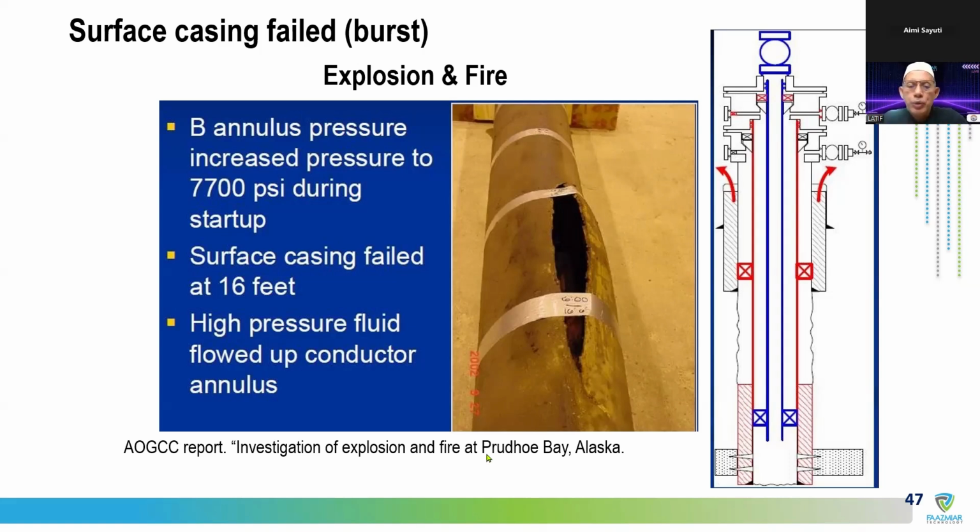Even to avoid further contamination, our drilling mud has been tested to make sure it will not affect the properties of cement, even though they are mixed. So that's a guarantee that even if we make some mistake, the drilling fluid will not affect the thickening time of the cement, and we are still okay with the cementing job.